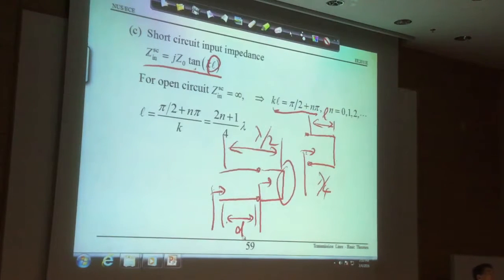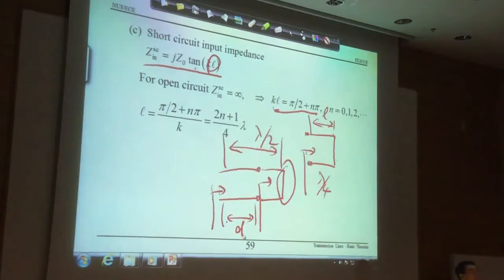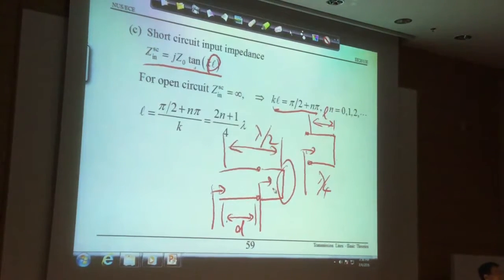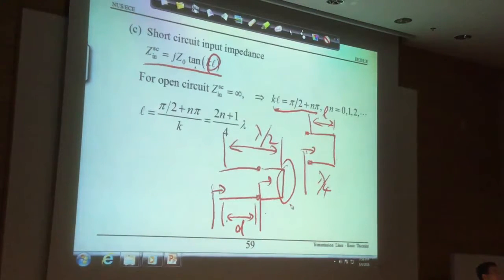Okay? So also, microwave is quite different from what you have learned in low frequency electronics. In low frequency electronics, short is short, open is open. Now, in microwave high frequency, a short circuit could become an open circuit after a certain wavelength. Now it's quarter wavelength, right?